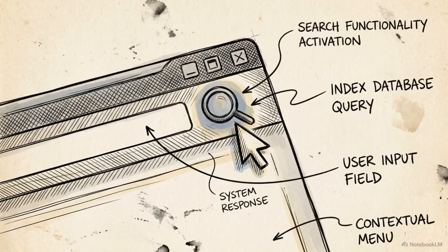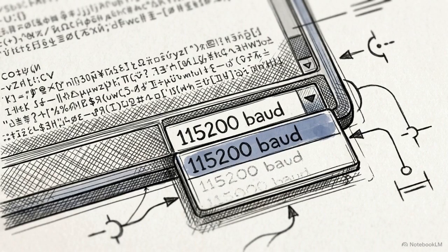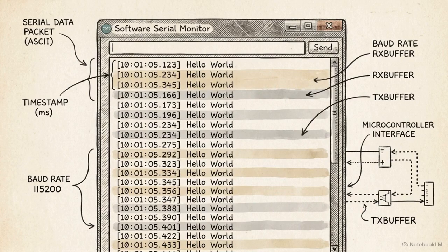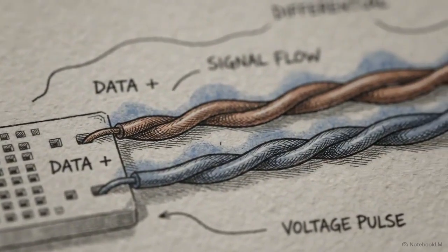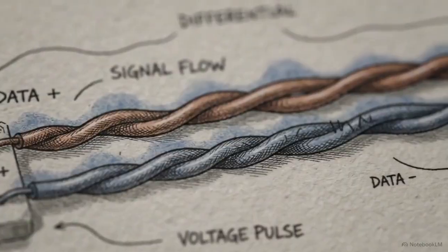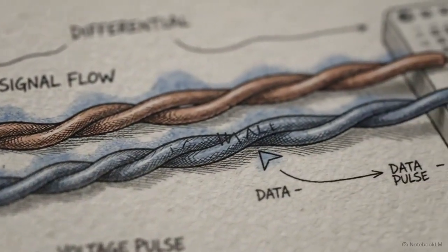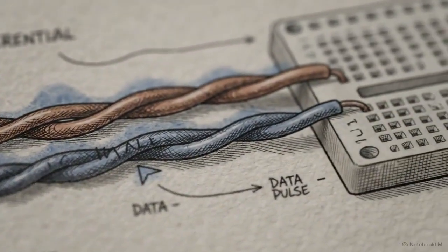To view that payload, open your serial monitor. Make sure you set the baud rate to 115200 so the incoming data renders clearly instead of appearing as unreadable characters. Once connected, you will see a continuous stream of Hello World packets populating the screen. You just created digital logic in code, converted it into physical 2-volt differentials across a wire, and decoded it perfectly on the receiving end.